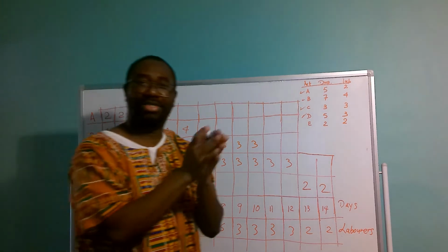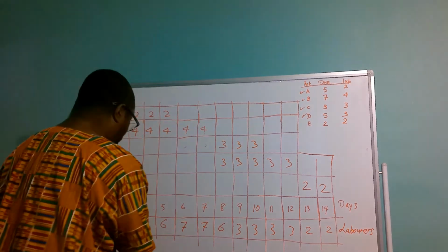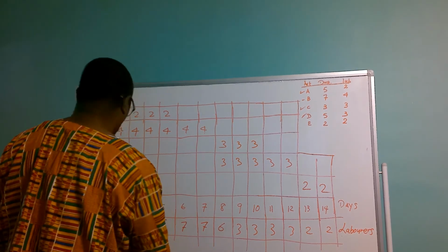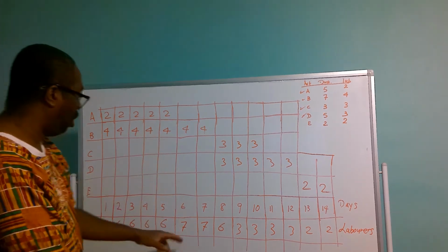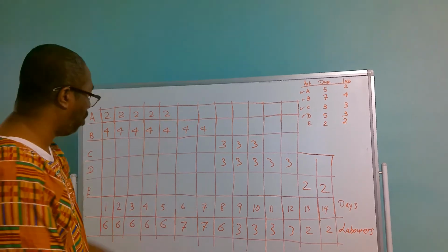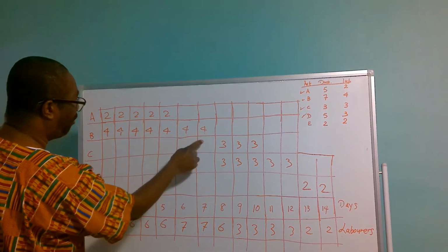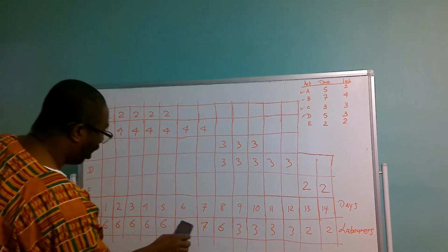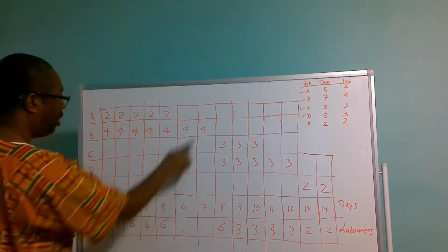And remember now C has 4 floating days. So he removed the labor force and the activity from those 2 days, day 6 and day 7, because you want to narrow this down. So if you notice now, the labor force for day 6 and day 7 will adjust down to 4, because 4 here and 4 there.